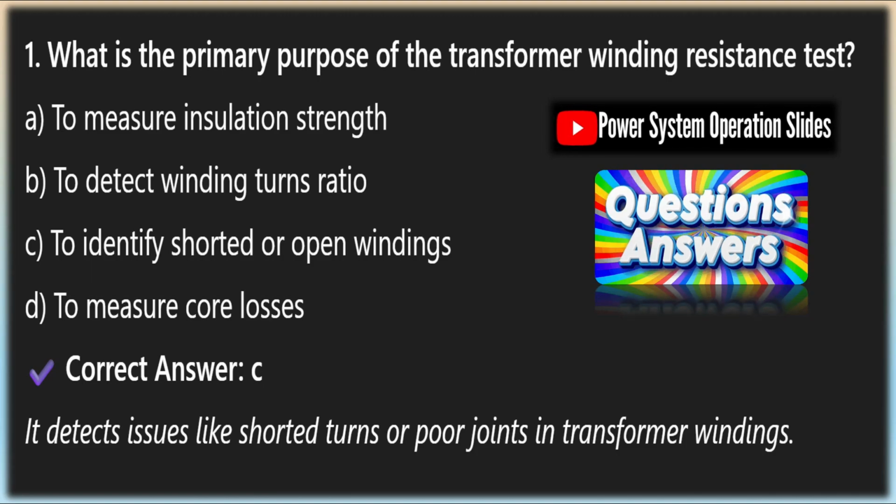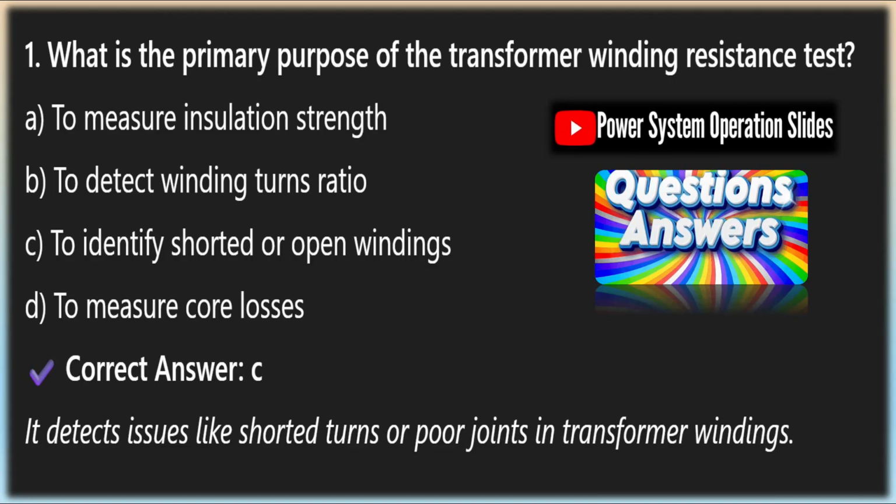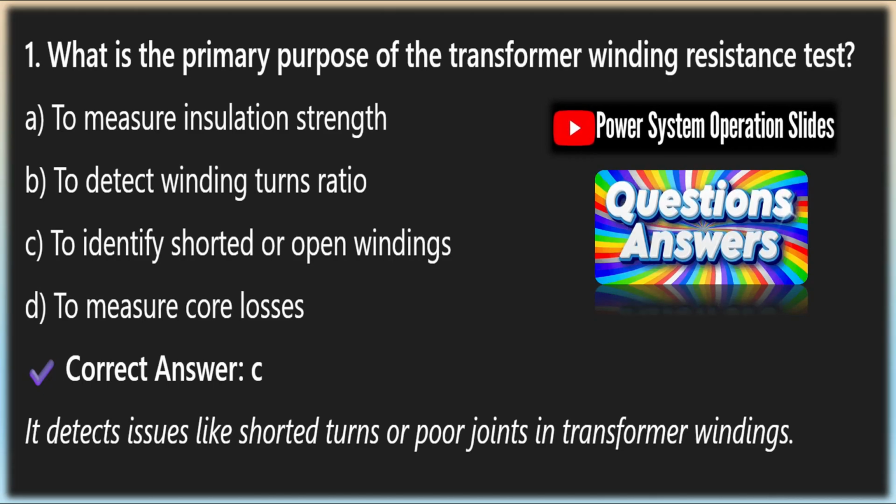Where possible, using dedicated test leads of known resistance and verifying their performance before measurement ensures that all readings reflect the true condition of the winding. Eliminating external errors provides confidence in test results and subsequent maintenance decisions.